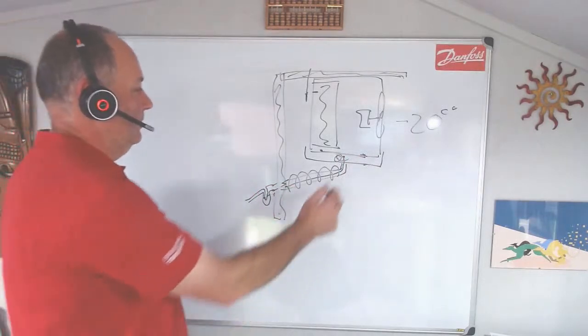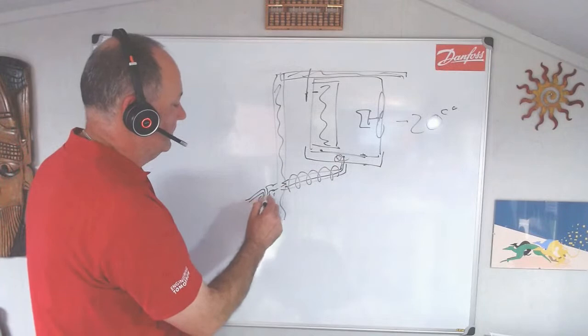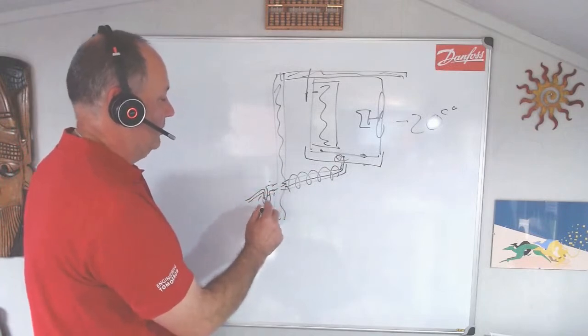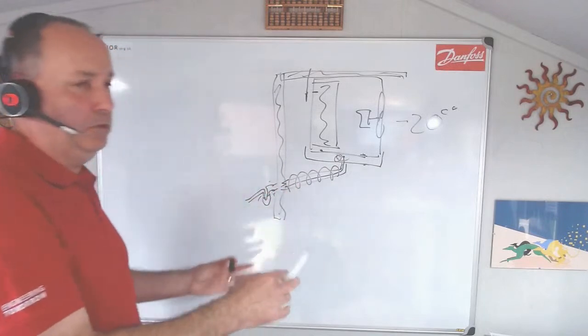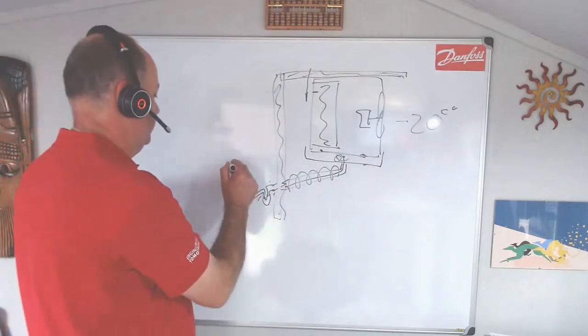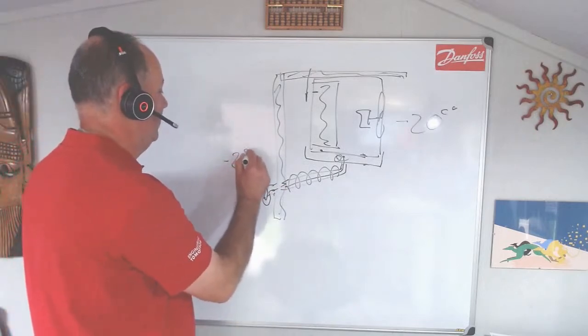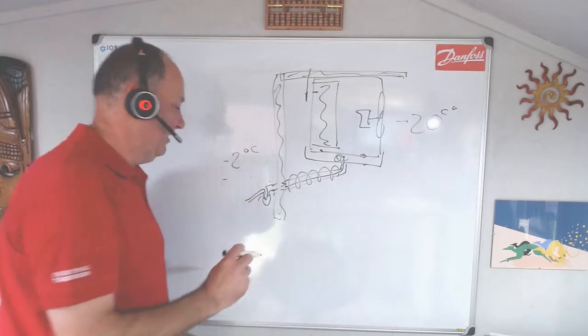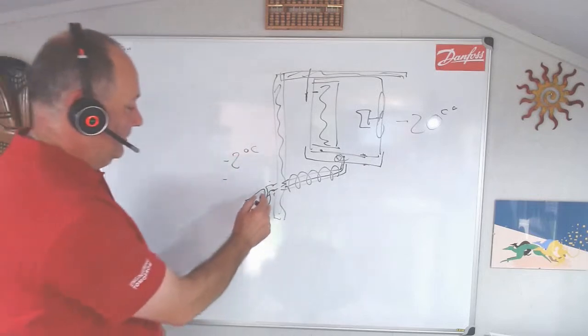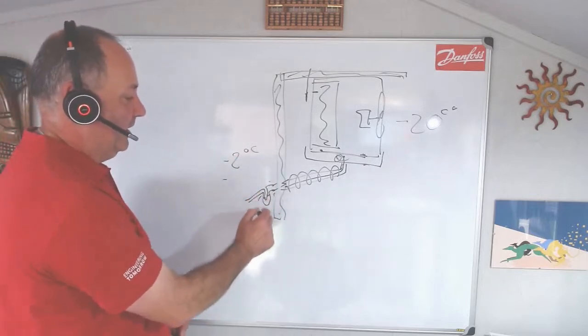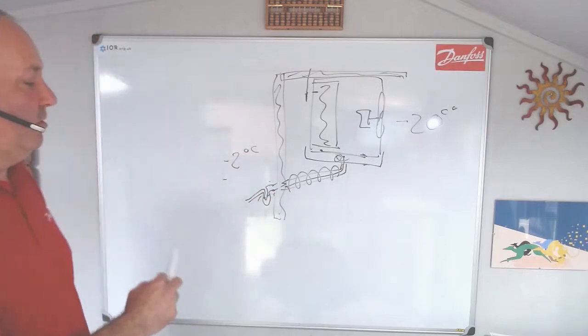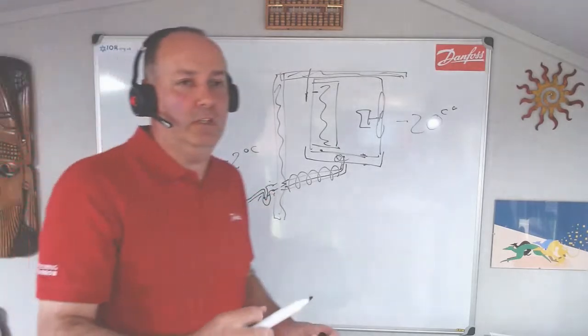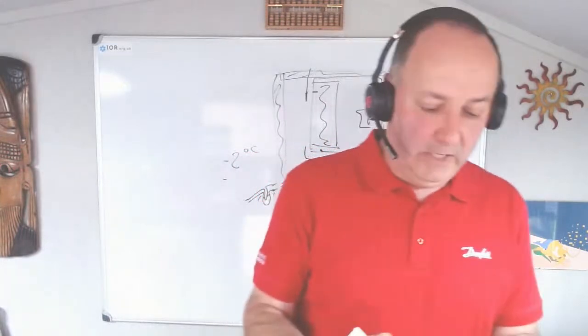So this trap here, if that is in the outside temperature, and let's say it's winter time, and I'll talk the UK, if that's, let's say, -2, which is a cold day in the UK, that would also need to be heated, but it would need to be heated all the time. So it very much depends on the application and the location of the drains.